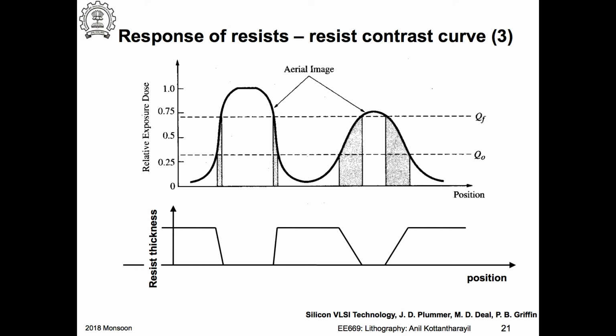Okay, so it is very difficult to do any imaging if the material you want to observe is dielectric using an electron beam, because what are you looking at in scanning electron microscopy? That is one name, but it is also called secondary electron microscopy. Yeah? So you actually have these electrons going and hitting the substrate, and they will emit,